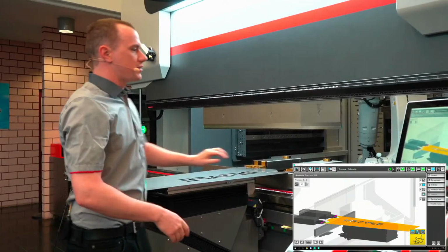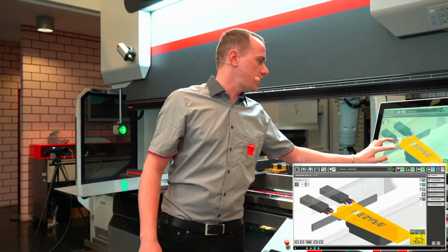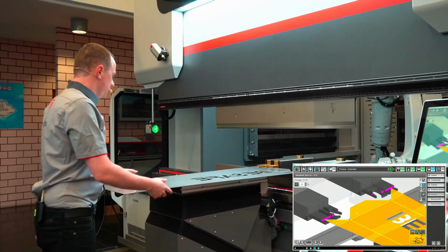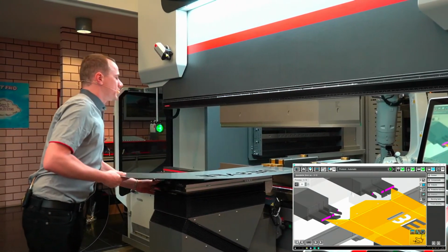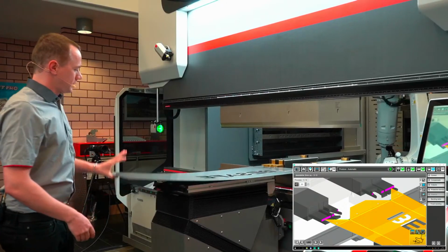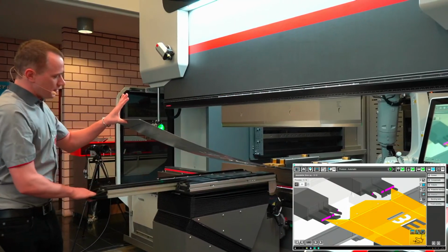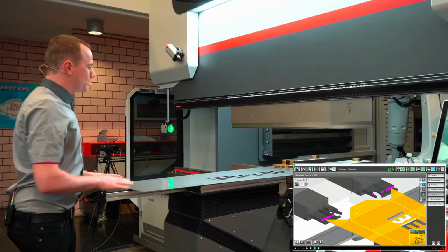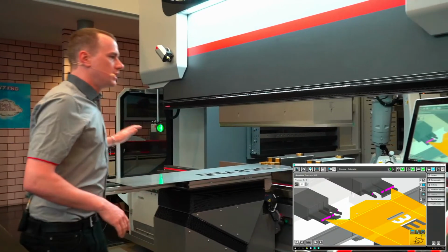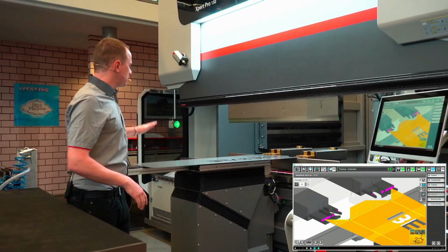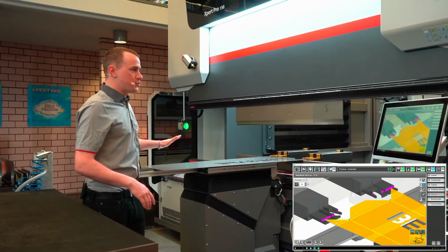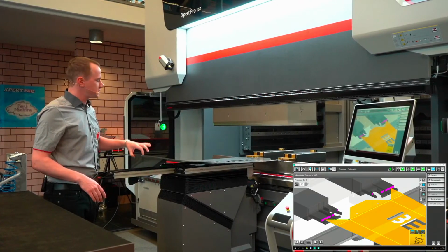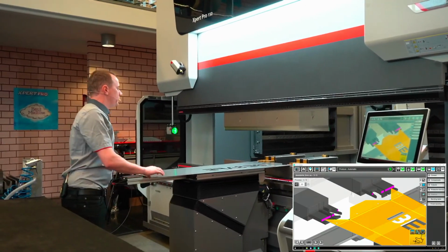I can also see very clearly on which position I have to attach the part to the back gauges, here in bright pink. So it's really clear where I have to put everything. Now I'm going to extend the bending aid, to really support the part. The bending aid is activated on this part, so it's a pretty helper because we see it's a very thin part, so when we bend this, it tends to bounce and maybe get damaged.